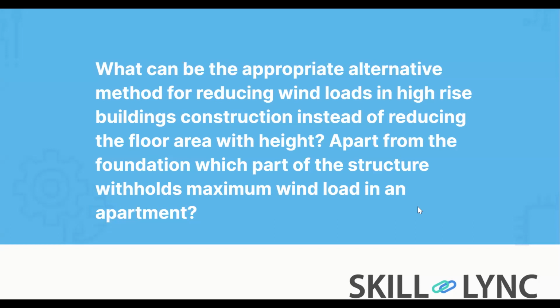So these are things that we do at a concept level with the architects, with the wind tunnel specialist. We sit down with them as structural engineers. We do certain studies and we tell them, okay, this wind load is too much. How do we try to reduce it? These are the various options that I said now. And then we decide through coordination and we come up with ways to reduce this wind load. So I think that answers the question.